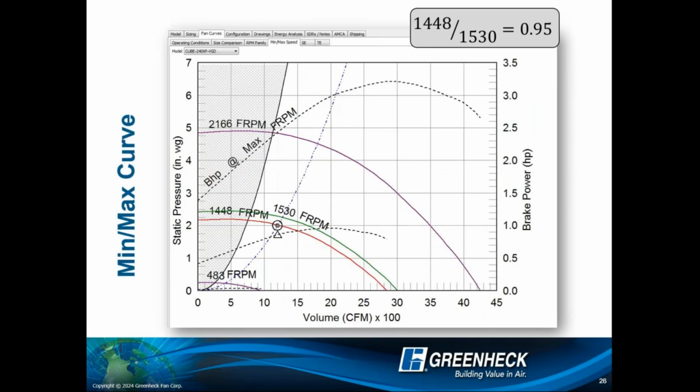Nope, that's awesome. And you're right. This on the screen kind of plays into both what Matthew and I are saying, right? Here I've only got 5% to turn up. Even within the horsepower recommendations by Matthew, if I just bump up to a horse and a half or a 2 horsepower motor, I added a little bit of cost, but I bumped up my range, so you can apply that across the board that way, right? I'm affecting my max RPM that is allowed.